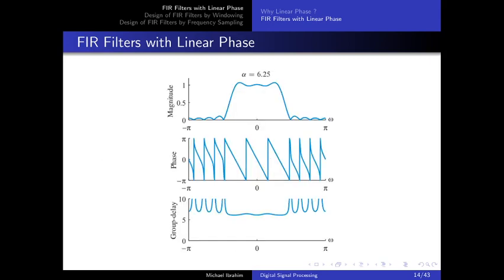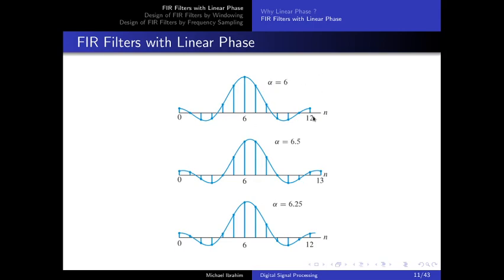In order to clarify, let's go back over here. Let's say we take the sample at 13. The sample at 13 was symmetrical with the sample at -1. Now that we've gotten rid of all the samples before 0, we cannot include the sample at -1. That's why we cannot include the sample at 13, because these two samples at -1 and at 13 are symmetrical. So in order to keep the symmetry, I need to keep both of them. But if I kept the sample at -1, I would have lost the causality. That's why I will only stop at m equal to 2 alpha.